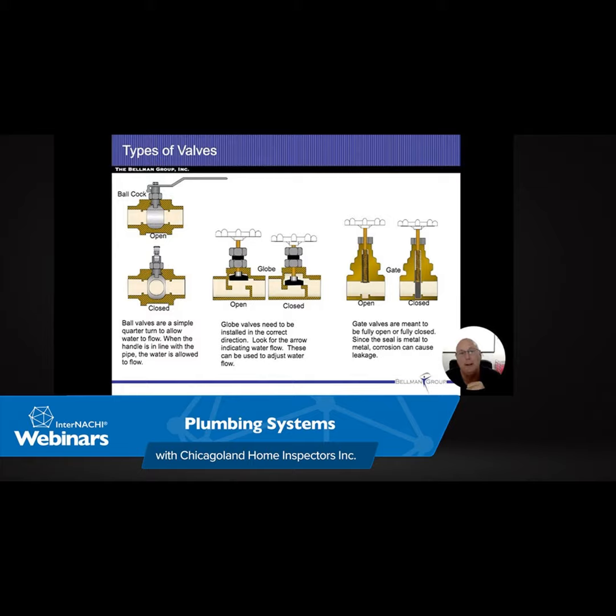If you start seeing soft temper, where somebody's bending water lines, and I'm talking anything other than a refrigerator ice maker line, those are typically soft temper copper, so people could feed them through the walls. But we're not supposed to take anything soft temper through the walls. It's flexible on a refrigerator line so that the refrigerator can move, all right? But inside the house, only hard temper, so it shouldn't be bendable or flexible at all.